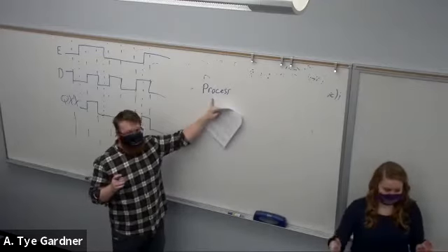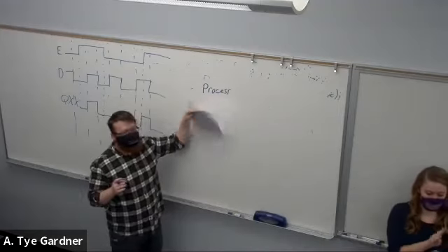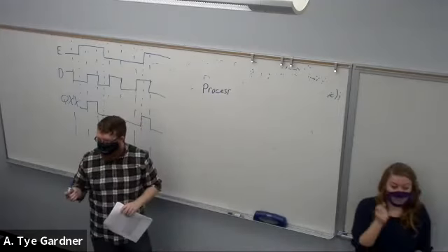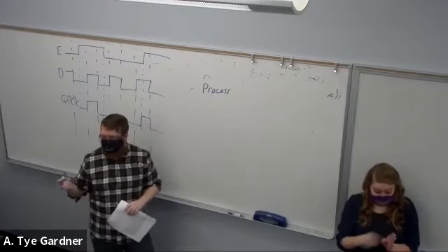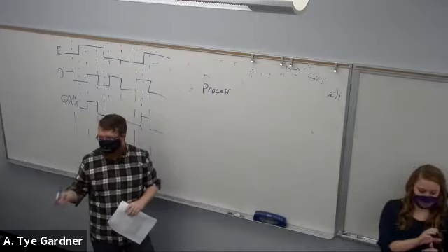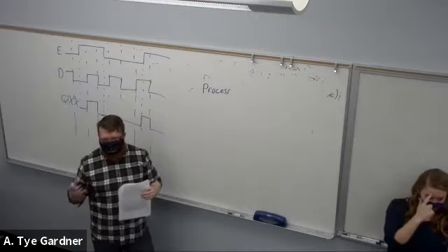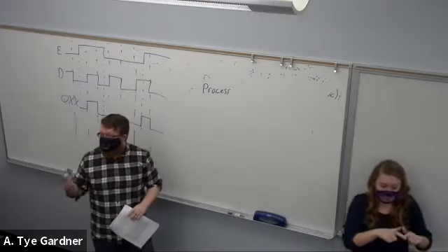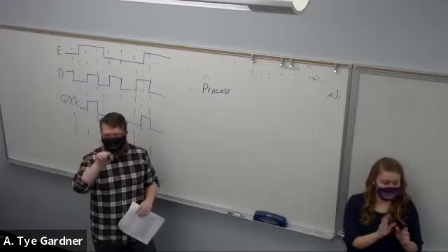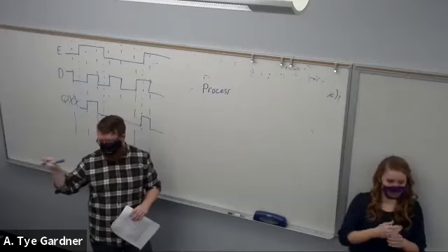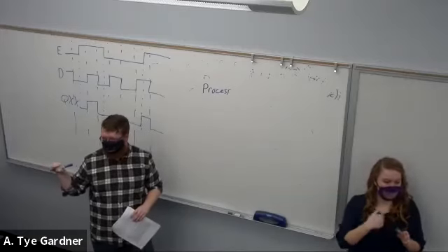Now, don't fall into the trap: a process does not necessarily mean it is sequential. It is actually possible to build combinational logic inside of a process. It just depends what you do. Like the mux that I showed you guys, and you can go inside of the Canvas files, notes, there's a file called mux implementations.